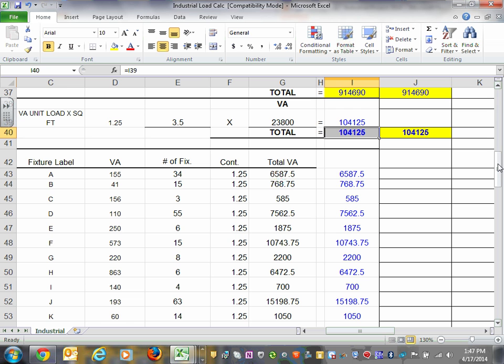So anyway, compare the two together, and I pulled this information basically. I allocated 104,000 volt amp, gentlemen, for my lighting load for this building. Now again, you can sit there and slice it down differently, get a lower number, but including the continuous load right into it. Any comments, guys, questions about that?